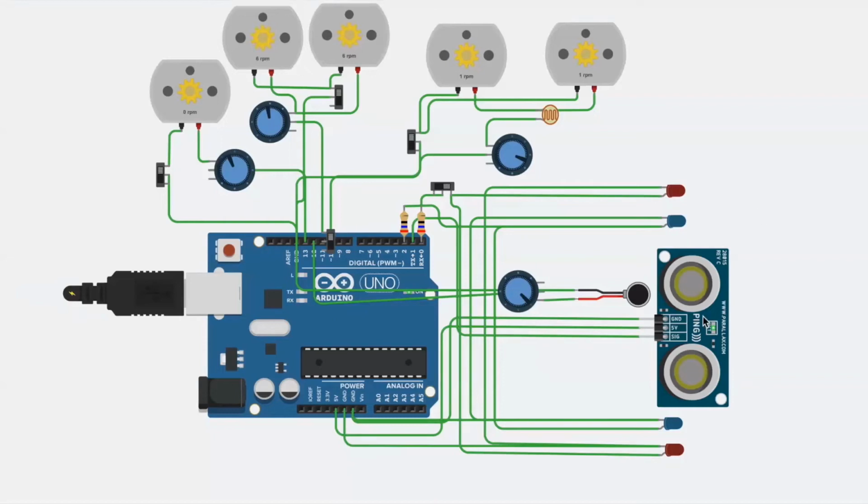It has an ultrasonic distance sensor. So when this ultrasonic distance sensor detects your hand under 5 centimeters, it activates the motor. And when this motor is activated, it acts as a pulley on the sanitizer bottle and thus releases the sanitizer. And the owner can change the amount of sanitizer being released and the time for the sanitization process using the code or the potentiometer. Once this process is completed, the blue light flashes and the vibrating motor starts to vibrate.